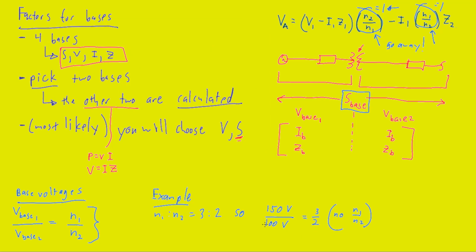What's important to understand and what we're accomplishing here is that for each section of a circuit which is divided by a transformer, we're taking a relationship and applying it to the base. We're taking this ratio relationship that we find in the turns ratio and applying it to each section. And when we apply that relationship to the voltage bases, that means we can get rid of our turns ratio complications. We're building it in, essentially, to the voltage base.